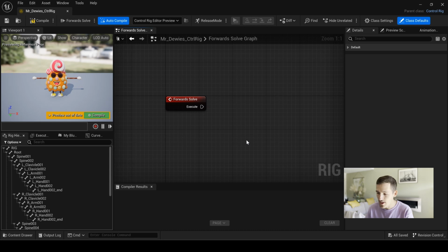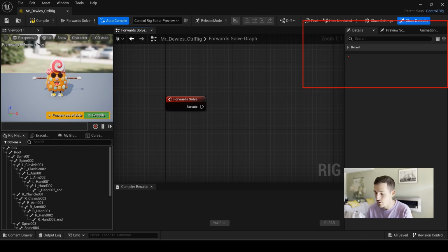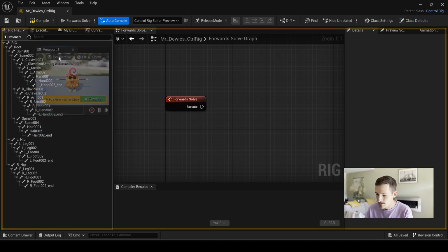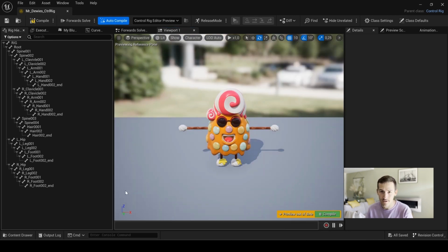As you can see, we have several tabs and we are going to focus on 4 of them. The viewports, all the tabs below, the graph, and the details area on the right hand side. As we're going to use a lot our viewports and our graph, we are going to customize a bit our UI. Select the tab of the viewports and drag it next to the graph tab. Now, let me explain in details what these are all about.